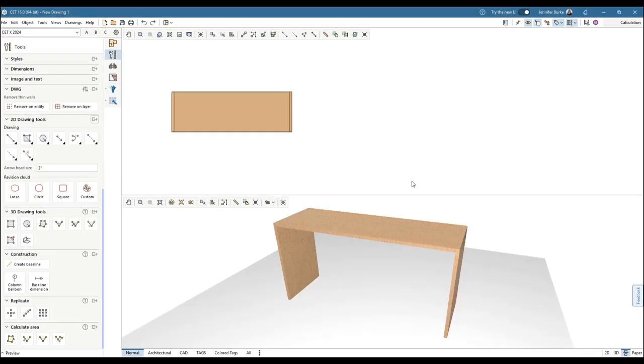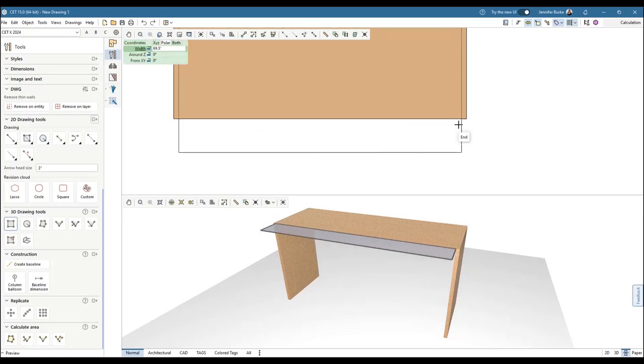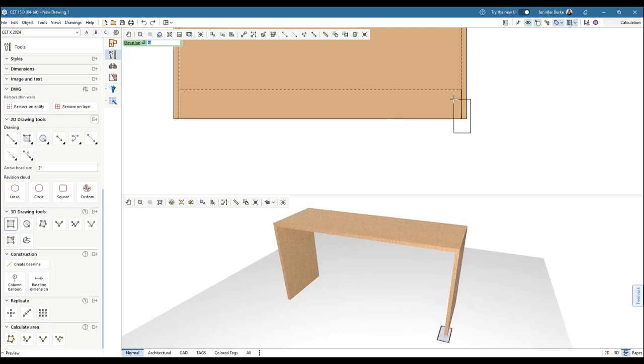The next step is to add that facade where the mail slots will be cut out. So we'll add that by using the rectangle tool again. Snap it on the inside of that upright, drag it over to the other upright, and then we'll go in about 7.25. The reason being is the depth of the mail slots is 6 inches, and I want to have a back panel shown so that you don't have a hole all the way through.